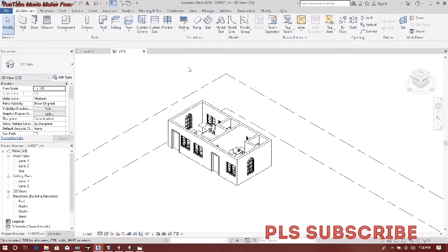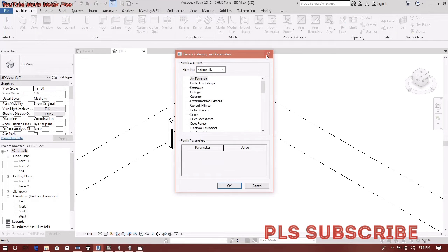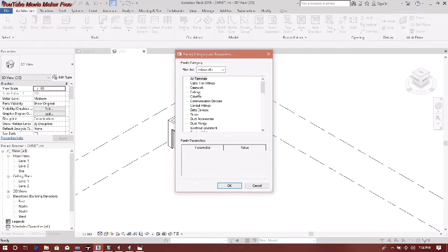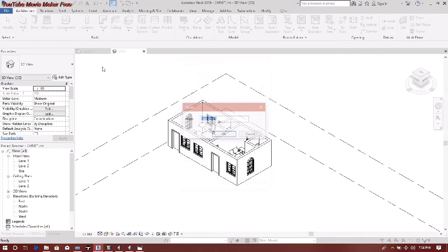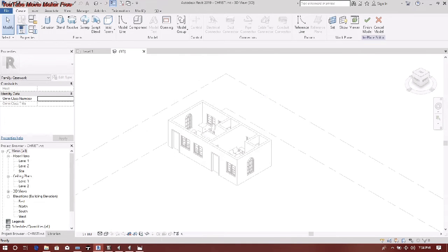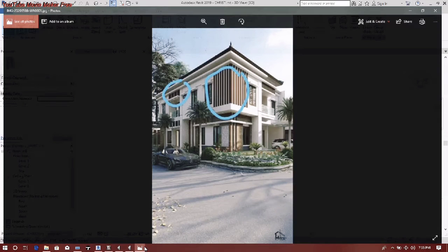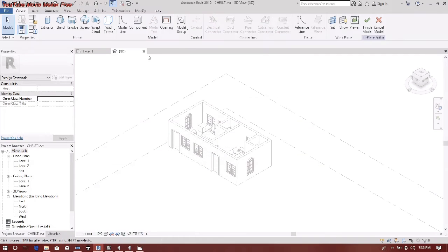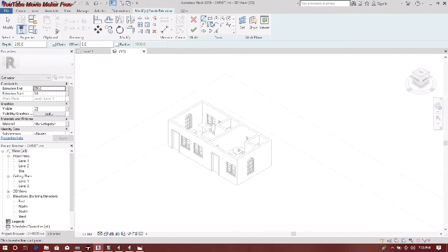After this, I want to explain how to put that on the wall. So you go to model in place, then you select model, the component and model in place. Go to casework. You have to rename it, or you just leave it as casework 1. Here we have extrusion, and for this type of thing we're using extrusion, but if it was something more curvy, you would have used sweep. Today we are using extrusion. Then you select the box.